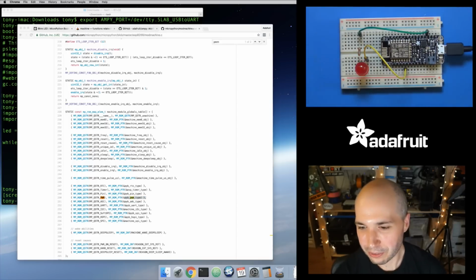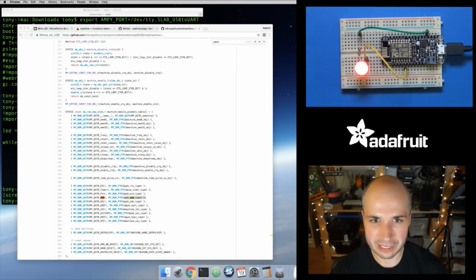Okay, long story short, I think that's it. Someone mentioned setting up a phototransistor to detect the LED and send signals to another Feather. Yeah, you could totally do that. That would be a cool idea to have boards communicating over visible light or an infrared detector and LED. That would be a great way to send data around between different boards. And simple, because you just need a digital input on both your boards. If you wanted to use a wireless radio, you've probably got to have an I2C interface or a SPI interface talking to some other module, and all this complexity, where it's just, I have two boards next to each other that need to send some data. Light could work. That might be a good option. Sound is another thing you could do too.